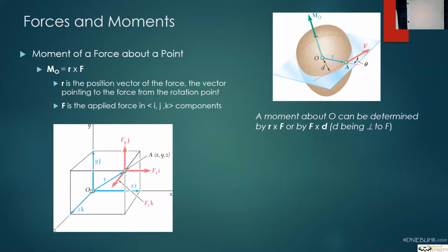And so you figure out that vector, and the R vector can be to any point on the force, which is nice. I recommend just take a convenient point where the force is well defined, but it really doesn't matter. Any point on the force will work.